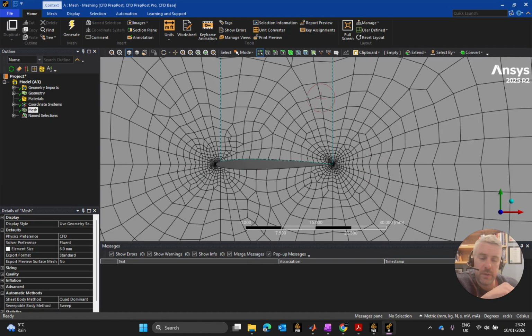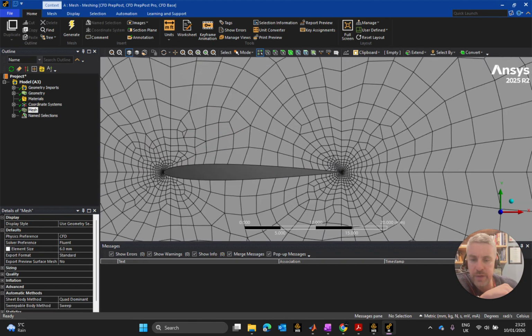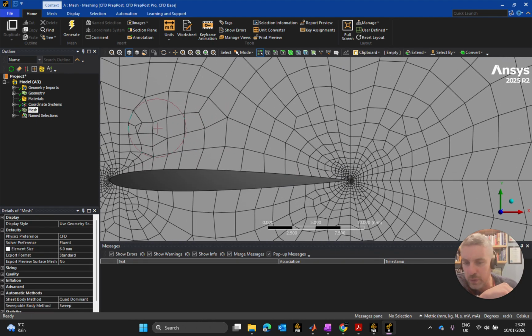If you choose to run with an unstructured mesh, it's fine. It's not as computationally intense as a structured mesh, though that comes with caveats depending on how finely resolved your mesh is. But what we have here are areas where skewness wouldn't be great, and aspect ratios and orthogonality aren't great.